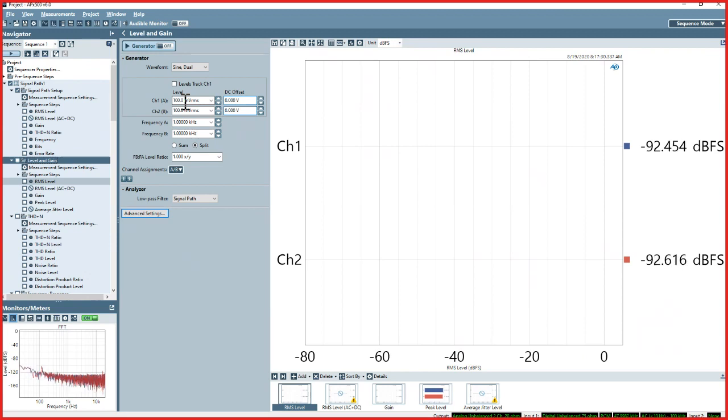Great. Okay. Thanks, Dan. Next question is about signals that are damaged caused by long cables with the DSIO module. Does Audio Precision have external buffers like the PDM line driver that exists for the PDM module? We do not. It is possible that that could be used. It depends very, very much on the clock configuration.